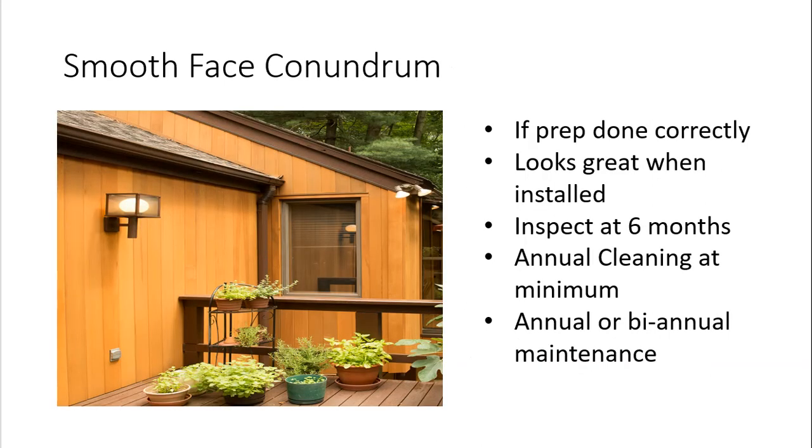Now, the reason the entire design community wants a smooth face is because it's gorgeous. If the prep's done correctly, it looks awesome when it's installed. All right, this is a picture of freshly installed smooth face. I mean, it is gorgeous. I don't deny that. To keep it looking gorgeous, you're gonna have to go around and inspect it every 6 months. You're gonna have to be that guy that loves to wash his car. Plan on and budget for cleaning it every year. All right. Plan on and budget for, depending on exposure, maintaining it every year, at least every 2 years.